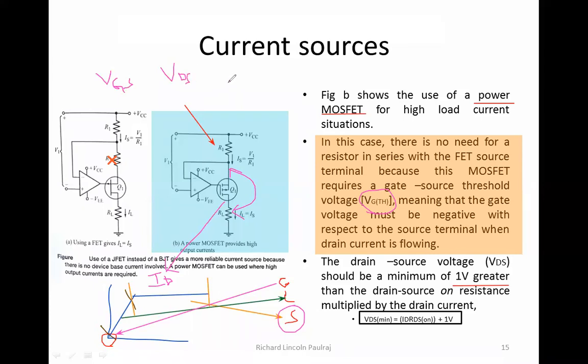Okay, so voltage across gate and source, and here voltage across VDS. So I should increase my VGS, and also I should increase my VDS. At one point, as I keep increasing my VDS, my ID, the drain current, will also start increasing, till what point? Till it reaches this point, till the transistor gets into saturation region.